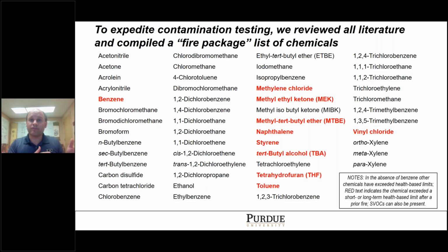What happened in Louisville, actually, and I didn't mention this, is that they lost so much water and so much pressure that they were concerned that the firefighters weren't going to be able to fight the fire anymore. So they bypassed their treatment plant and allowed untreated lake water to enter their distribution system so they could have water to fight the fire. Now, when they did that, they put untreated lake water into their distribution system, bypassing the plant. They were concerned about bacteriological and microbial quality.